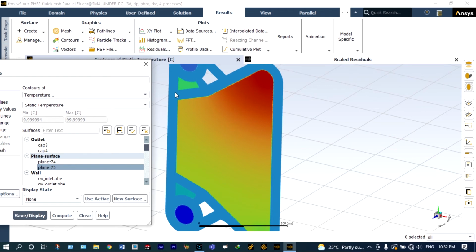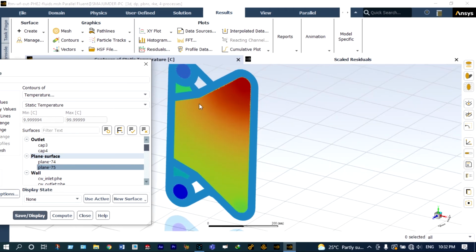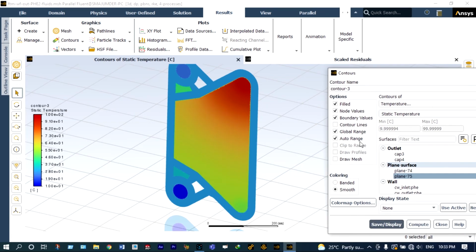This is temperature distribution through a specific plate. From the top side we are providing hot water, and while hot water is passing in the forward direction, it is having some kind of space in the left hand side, and this hot water is spread throughout the left hand side, and finally it is coming downside. The temperature indicates that downside temperature is in the range of 46 to 55 degrees centigrade, and top side temperature is in the range of 90 to 100 degrees centigrade, right? This is regarding one plane.